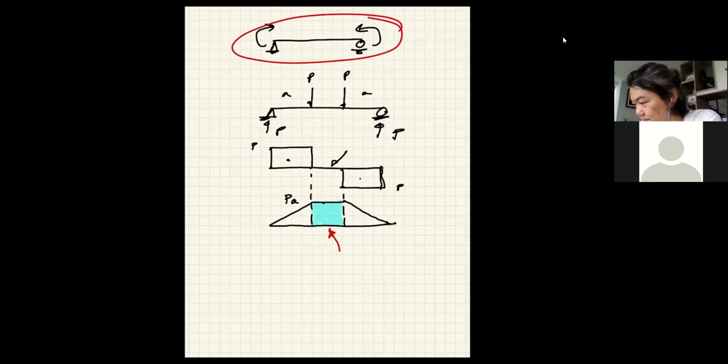I can erase the support, and that becomes the free body diagram of this piece. I just look back and wonder if, in our material testing lab, it means that the self weight is eliminated. I was going to say that, but you are quite quick. Self weight has to be neglected, not eliminated. Let's say it's minimal compared to this moment. Of course, it's there, and you will never have truly zero shear.